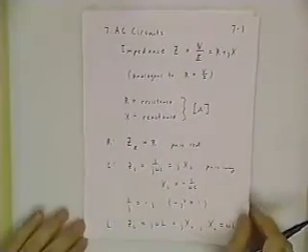Now the whole idea is to go from an AC circuit with defined sources with resistors, capacitors, and inductors. And if I know that AC source frequency, I can convert the entire circuit over to a phasor and impedance model and then apply exactly the same circuit techniques that I used for DC circuits. The only thing is now I have complex numbers to deal with, and that just makes the arithmetic a little bit tedious and nothing more. It's conceptually exactly the same as we talked about already for DC circuits.